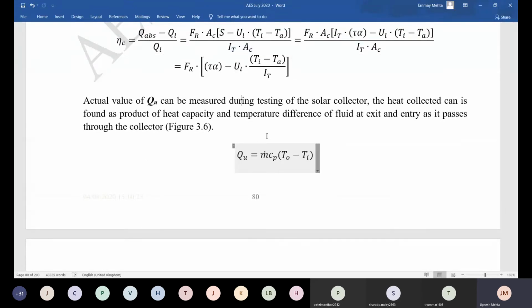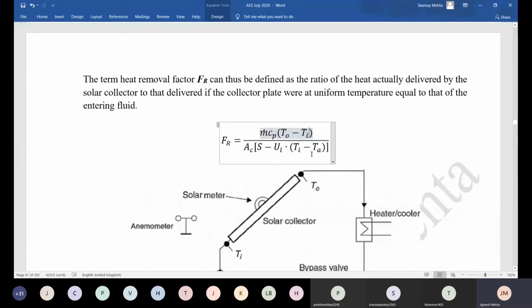So you know the useful energy. The other way to measure the useful energy is to get m Cp delta T. Let's say you're heating water. So what you're doing is you're pumping water. Forget about the domestic water heater where there was natural convection. But if you are pumping the water, then there is the mass flow rate of water, the temperature difference created, and the Cp of water. That's your final product that you want to get. So that is also useful energy.